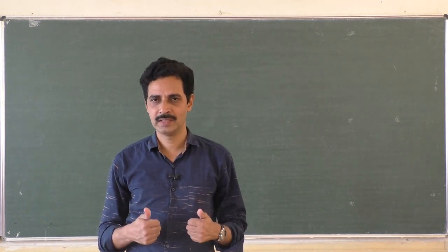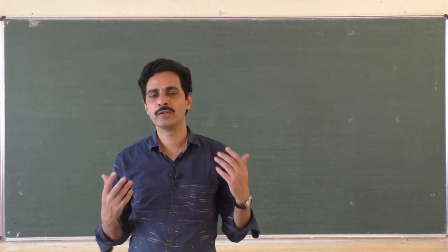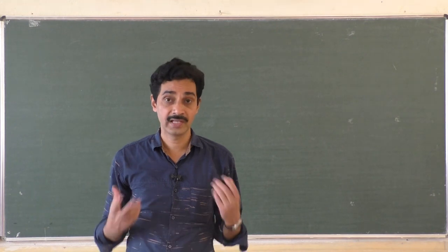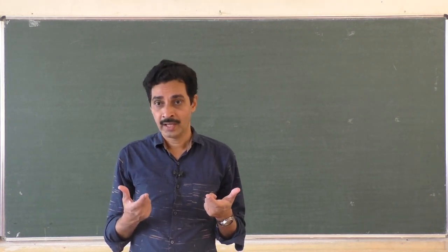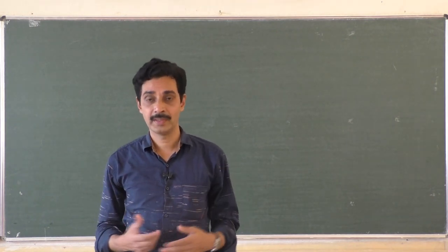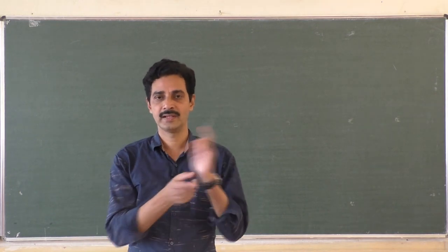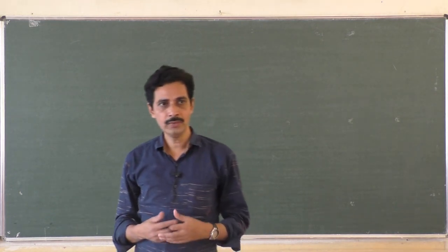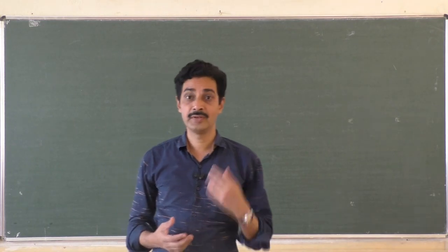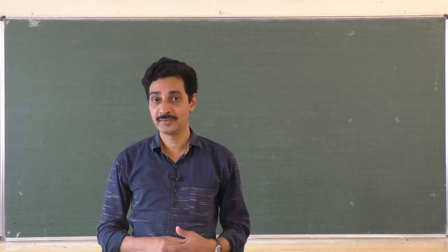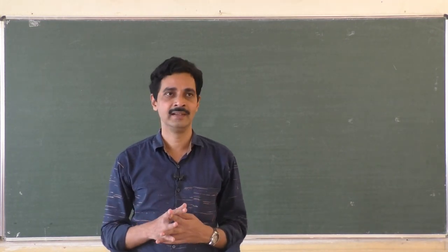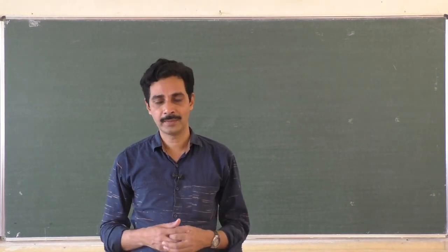Only the resistor will be in charge, right? So all the voltage appears across the resistor. Of course, there is a voltage drop across the inductor and capacitor also, but they cancel each other. You know the phasor diagram, they are exactly opposite. Only the voltage across the resistor will be the full voltage, and when we work out problems we will see whether we get the same situation or not. But still the theory of this chapter is not yet over.